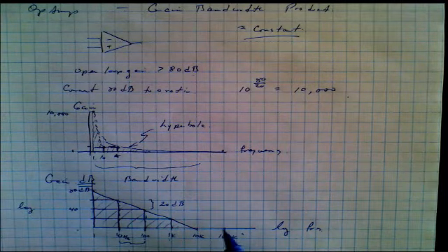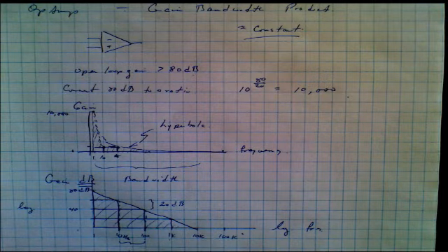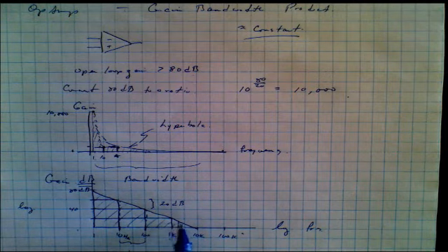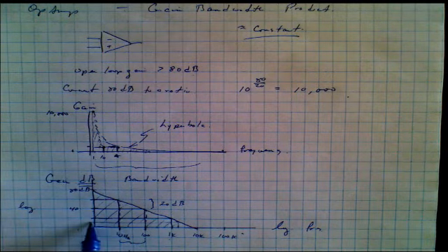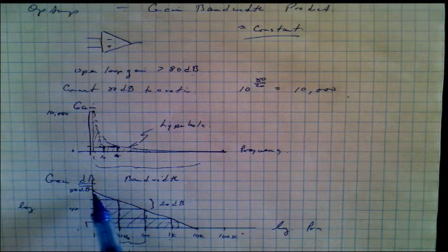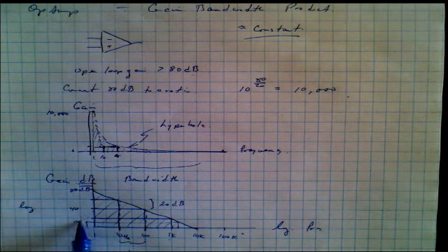So for example, in this particular circuit, let's say that we're going to build an audio device. Well, a typical telephone operates only up to 3.5 kilohertz. And that's someplace in about here. And notice we could use this amplifier and its gain would probably be in a neighborhood of no more than 10 dB.